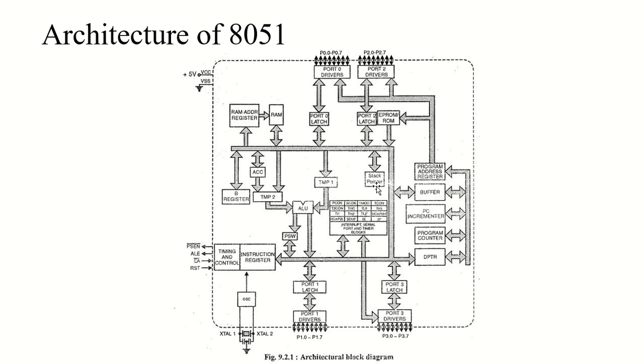Now this stack array can reside anywhere in the chip, right? But its height is limited to the size of the internal RAM only, and the stack can overwrite the data in a register bank as well, right? So bit addressable RAM, scratch pad RAM areas, such places.